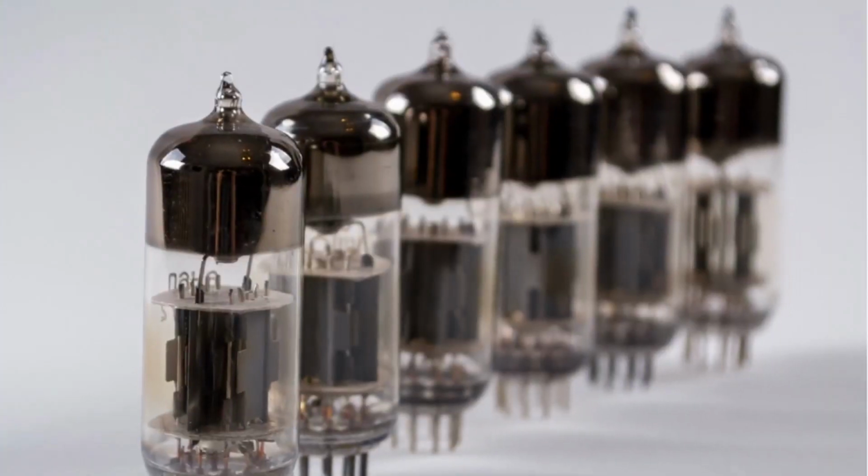The early computers, such as the ENIAC, used vacuum tubes. A vacuum tube is made of three components: the anode, cathode, and the grid. If we supply an electrical current to the cathode, it will emit electrons, and this process is called thermionic emission. Electrons emitted by the cathode will be attracted by the anode of the vacuum tube. We can complete the circuit by supplying positive voltage to the grid, and we can turn off the vacuum tube by supplying negative voltage to the grid.